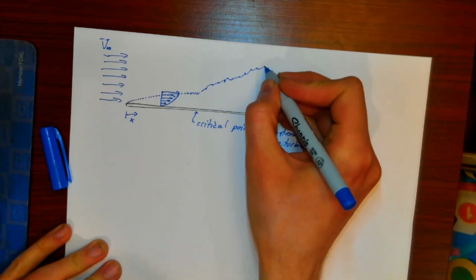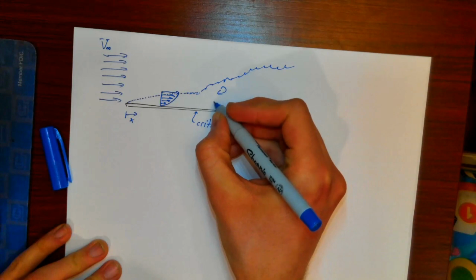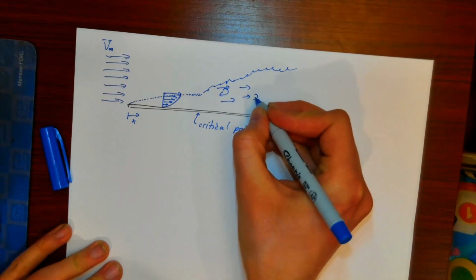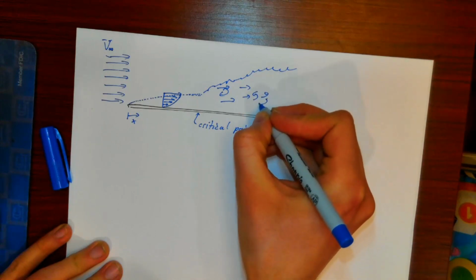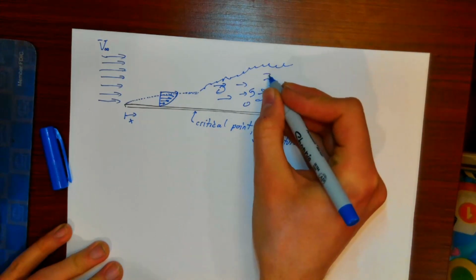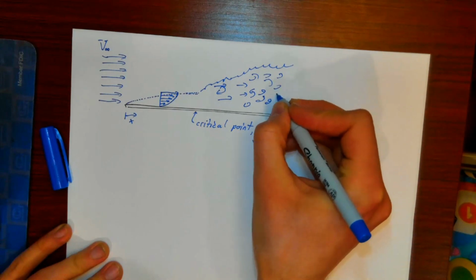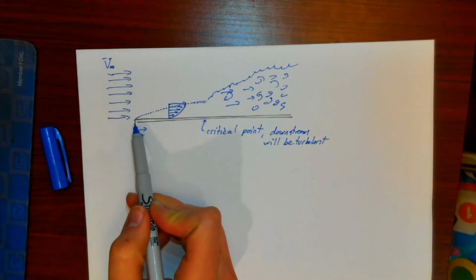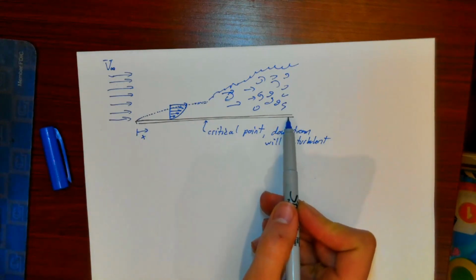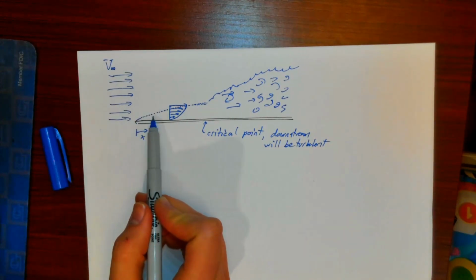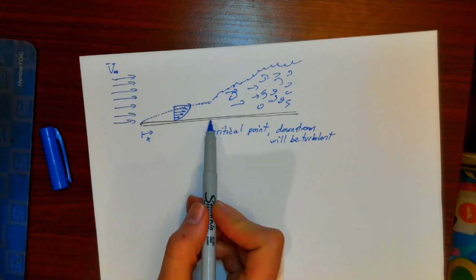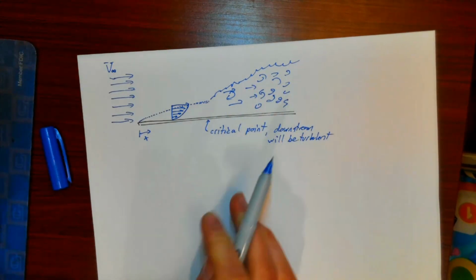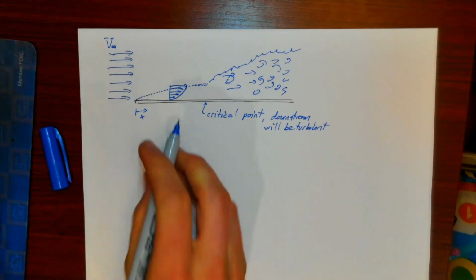And in these turbulent boundary layers, we end up with a lot of fluid that's mostly moving in one direction, but also has a lot of swirling, chaotic mixing and all of that stuff. So a lot of times if we have heat transfer from a plate, we get this laminar boundary layer that grows for a while, then there's some critical point after which the flow essentially trips itself into turbulence.